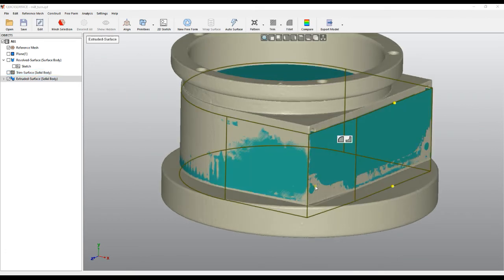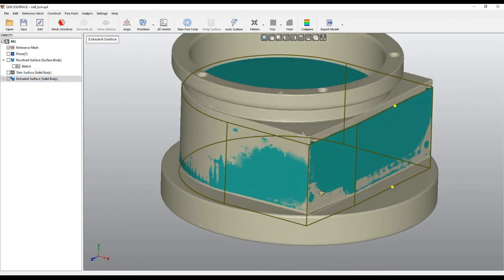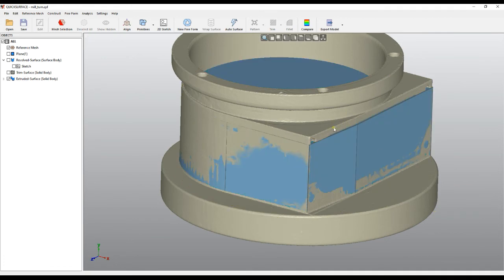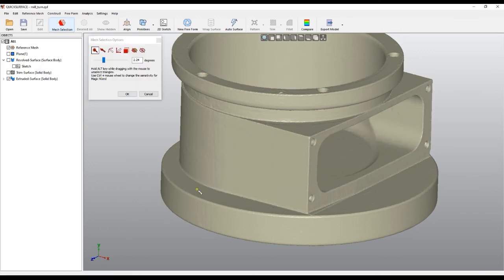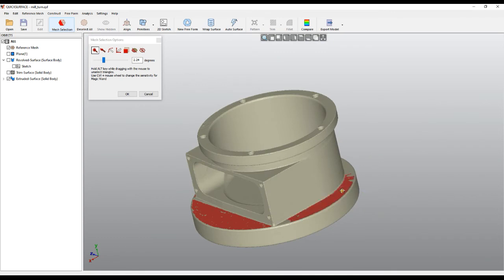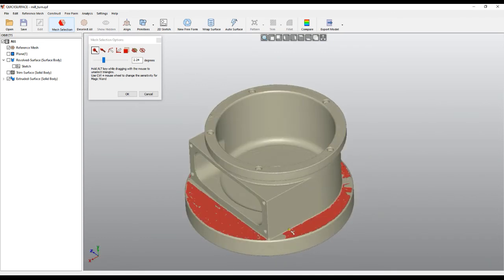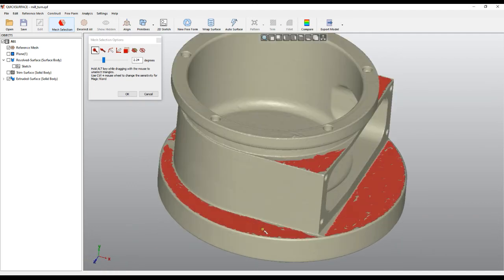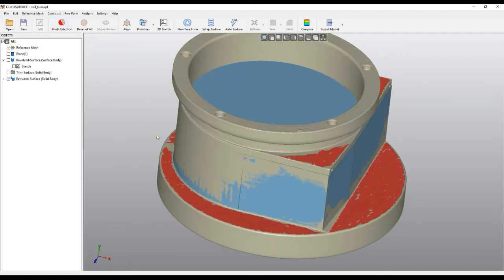So I select my extrusion, and before that I will select some areas which are my limit surfaces, which are my planes where they need to stop. So I'll just use my standard tools like this one. Click here, so I define my planes. Then I can select on the top, and I will now press OK. So the selection still remains on